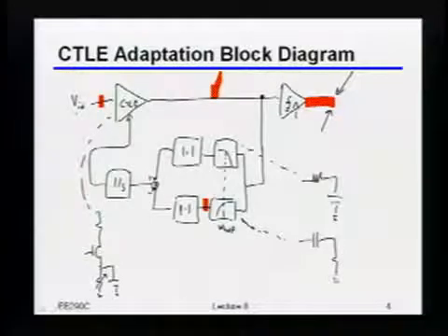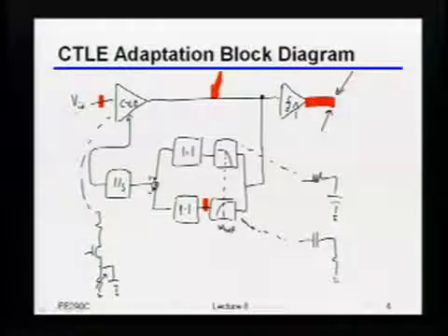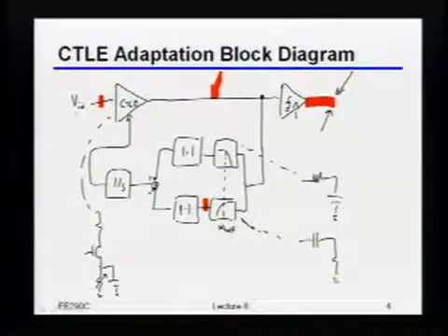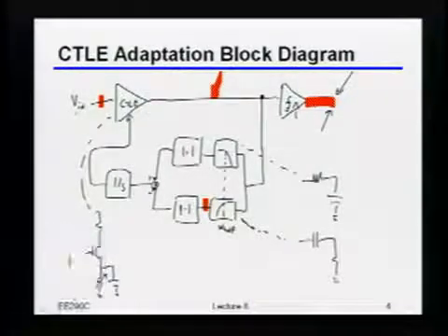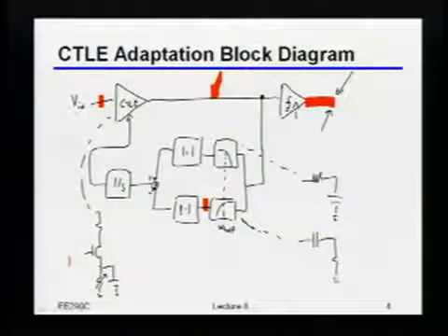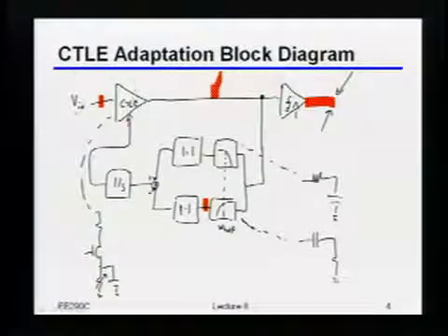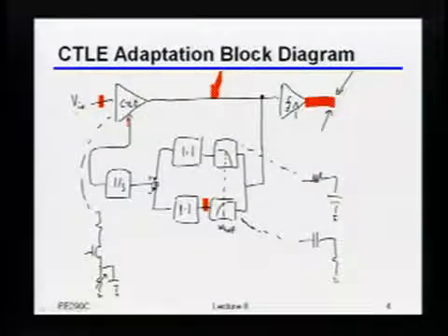Meaning I'm already so badly mistuned that my link is not working, and me tweaking things is not going to work. Right. So if you have more than one port, do you chop it off into further? Okay. That's a great question. You could indeed start chopping things further. You have now multiple independent things that you have to play with. That gets pretty complicated pretty quickly. And it turns out that for most of the practical link channels, people don't tend to peak it with more than 1 zero. They'll maybe do 2 zeros, and if they do, they may even fix where one of the zeros is and then just bite it if it's not exactly tuned correctly.